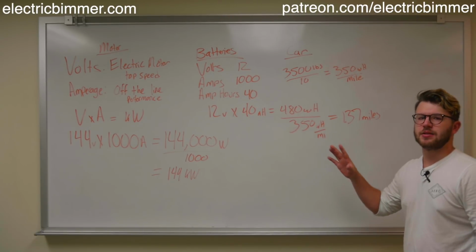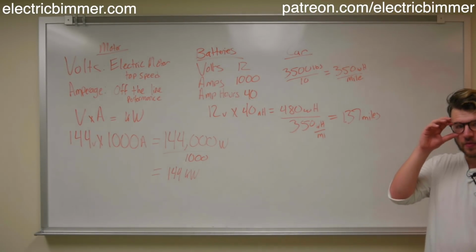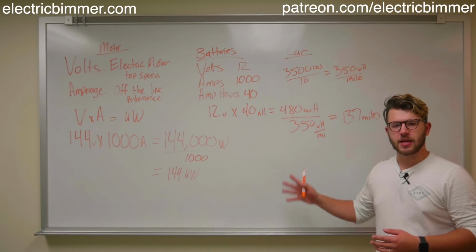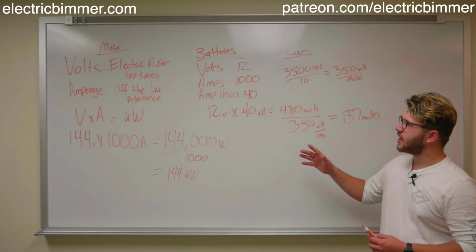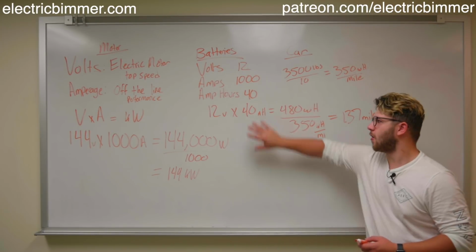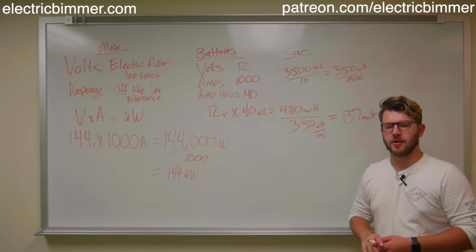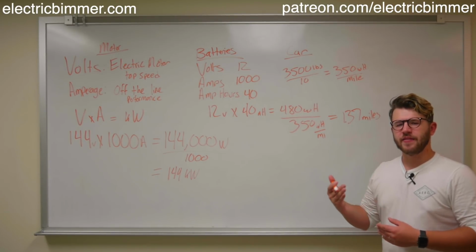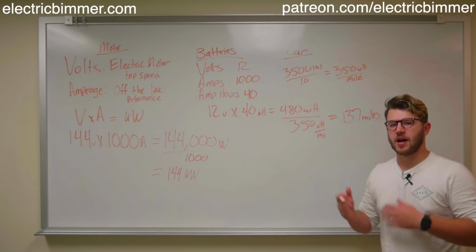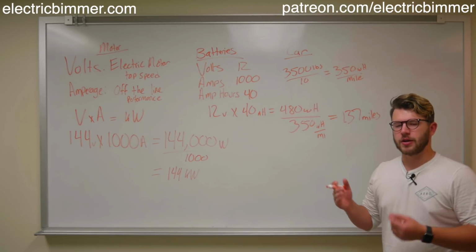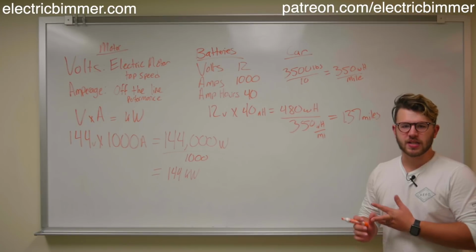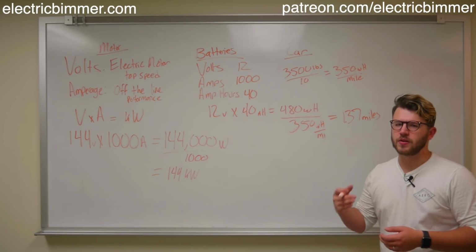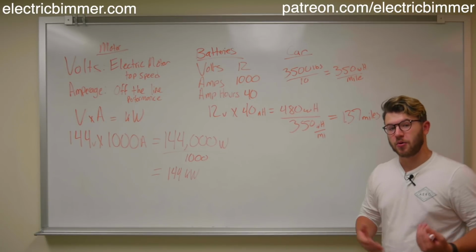Now we have this answer in miles, but there's a very big thing you have to remember about batteries, especially if we're using lead acid batteries. I'm going to redo these calculations for lithium, but for lead acid, you can't really use all of the available resources in there, just due to their chemistry. You can use about 50% of it, and even then you don't want to use that full amount, because after that 50% mark you're going to damage the battery. It likely won't put out as much power, it won't recharge, and there's a chance that it could explode if a lot is being pulled from it.